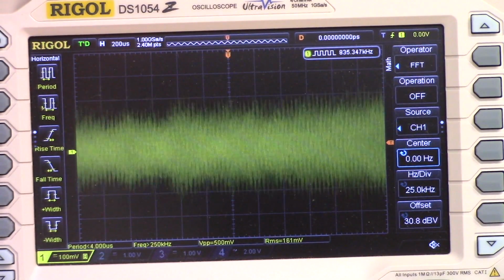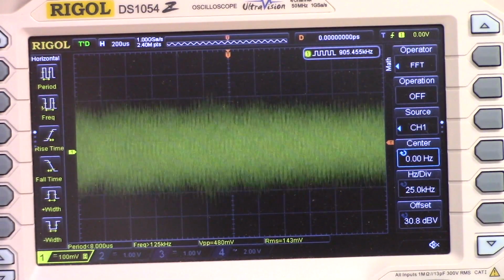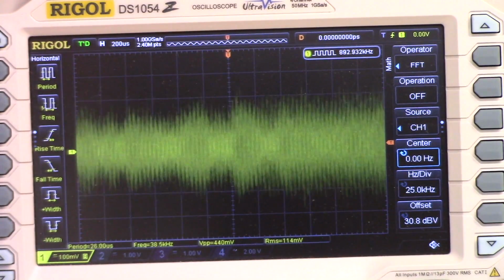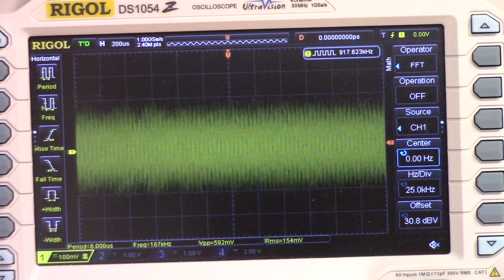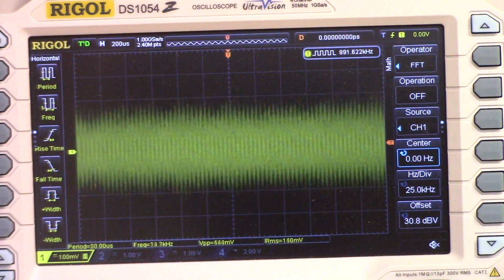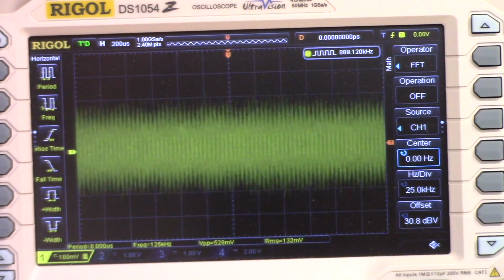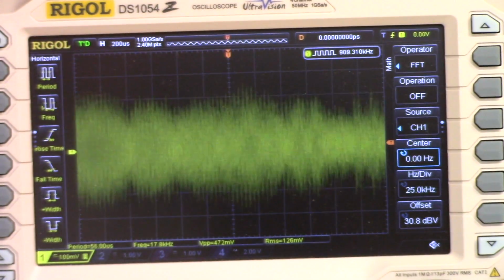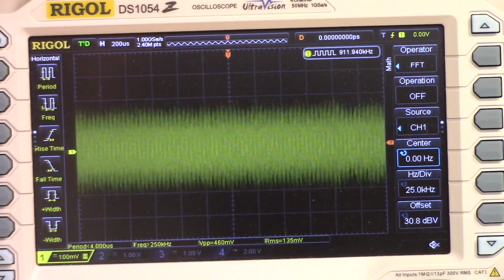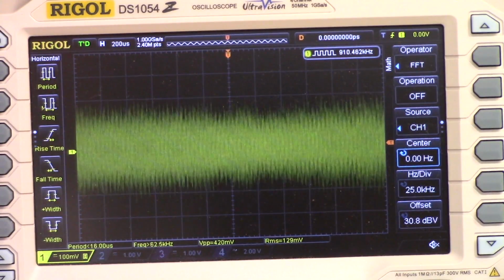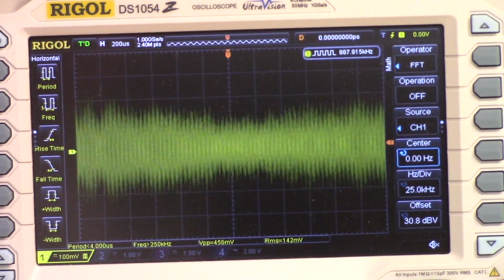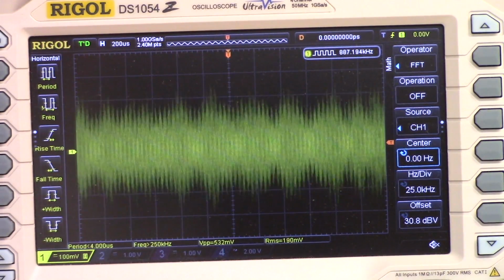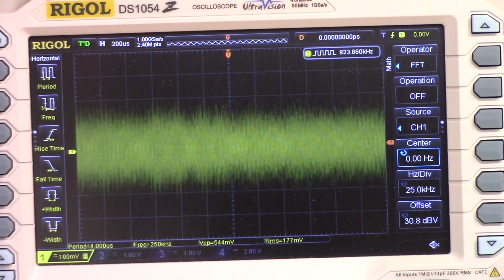Now, I don't want to infringe on any broadcaster's copyrights, so I'm not going to do what I'm about to describe. What you can do is measure the voltage by an oscilloscope from a loop antenna without any capacitor in the circuit, and then tune across the radio band. This works particularly if you are in an urban area where you've got several broadcasters. And for several of the AM stations, you will see with your eyes how the voices correlate with what you see on the oscilloscope. But it won't be a perfect correlation.